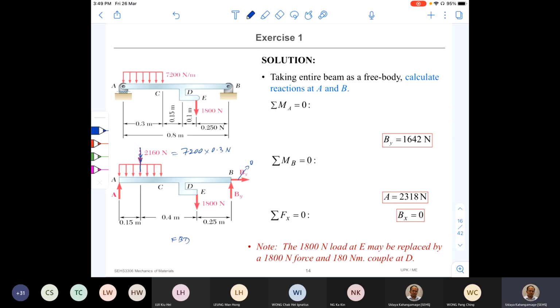Okay, so the dimensions are given. And now the first step is to find the reaction forces at A and By. So shall we start? In order to find the reaction force By at B, we need to apply the equation of equilibrium. It is easy if we take the moment around point A. The sum of the moments around point A should be equal to 0. Okay, so let's mark the positive direction as anti-clockwise. So now could you write the equation?